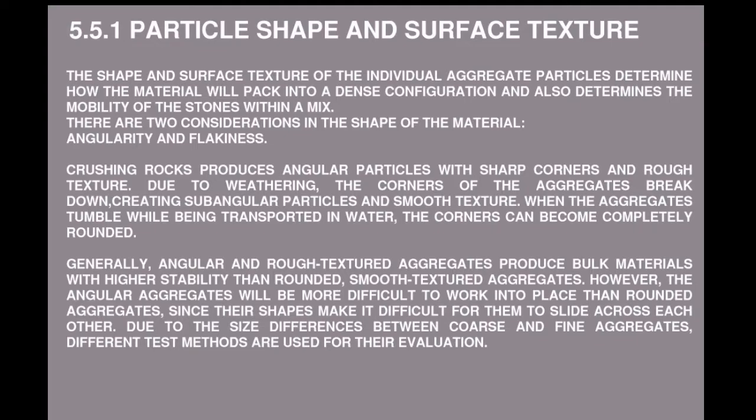The shape and surface texture of the individual aggregate particles determine how the material will fit into a dense configuration and also determines the mobility of the stones within a mix. There are two considerations in the shape of the material: angularity and flakiness.